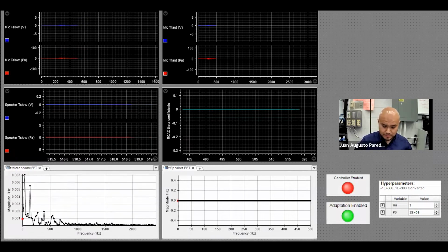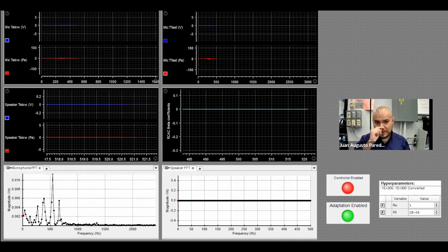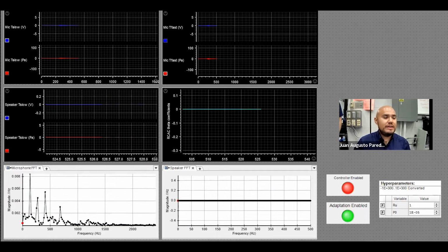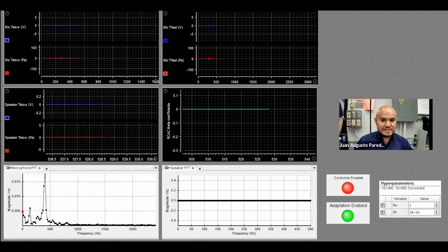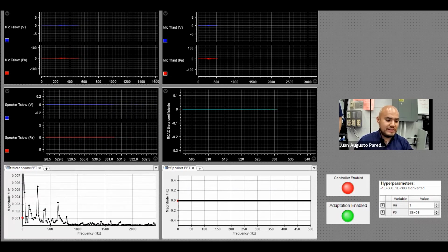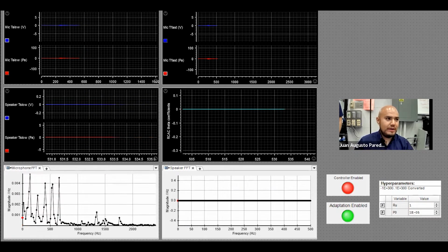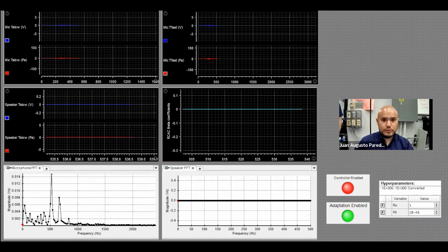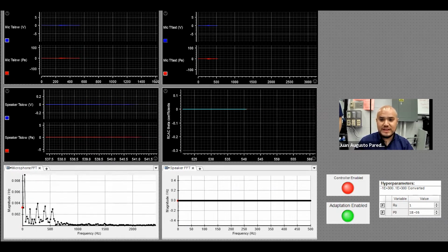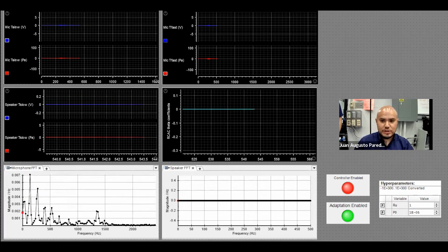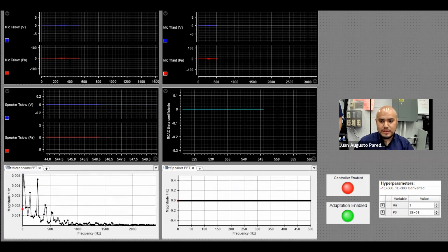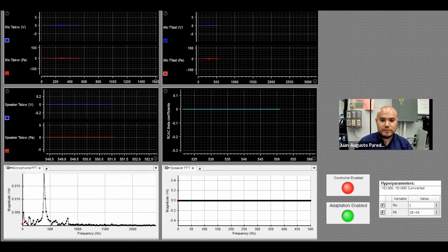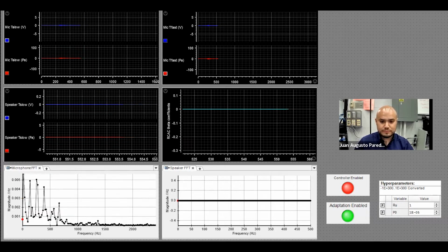Okay, now we'll get it started. In order for you to better hear the experiment, we'll be passing around one microphone at the start of each test so that we can better capture the pressure oscillations. So without further ado, we'll proceed with the first test, which is a static test with the coil placed at 0.4 meters above the tube bottom and supplying 75 volts of voltage RMS power.